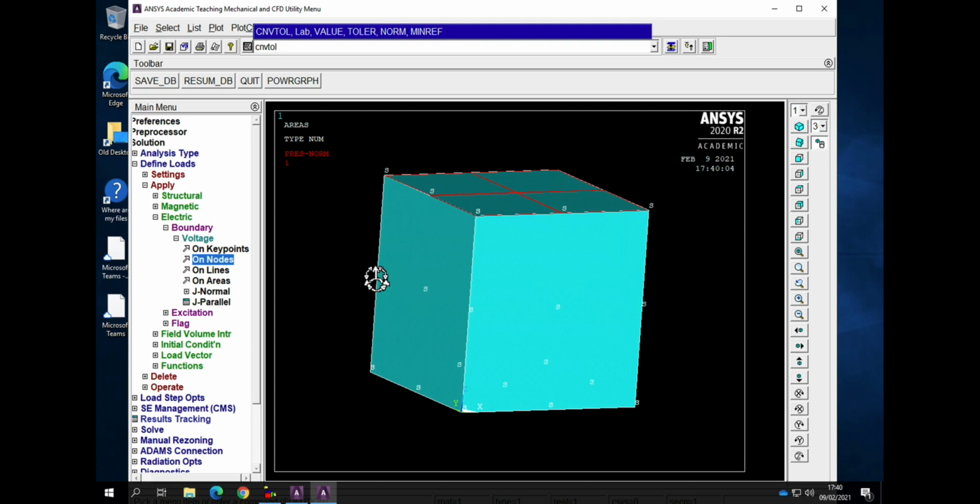So it's convergence tolerances in force, and we just know from experience, setting it to a small value for convergence of force 1e to the minus 6, and the same convergence tolerance for amps, and 2, 3, 4, 1e to the minus 6, and convergence tolerance volts, 1, 2, 3, 4 commas, 1e to the minus 6. That helps with the solution.